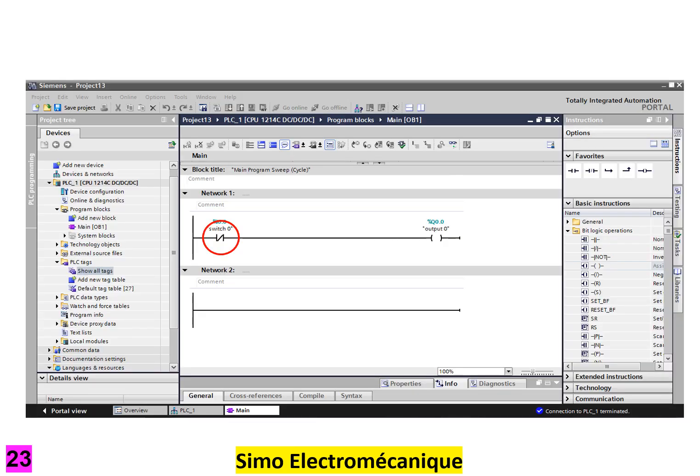This time we will look at the effect of changing the input from normally open to normally closed. A normally closed contact effectively reverses the input logic, the switch position. So if the switch is on, logical 1, the normally closed contact is off, logical 0. Create the ladder program shown.